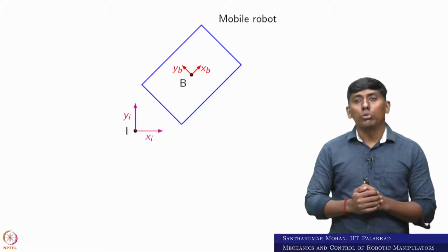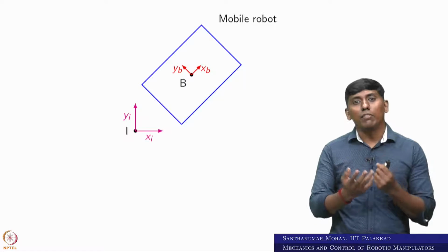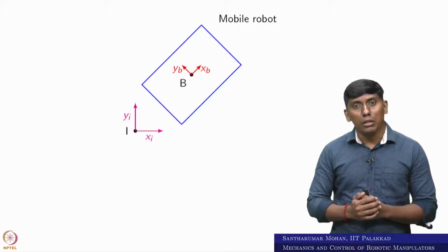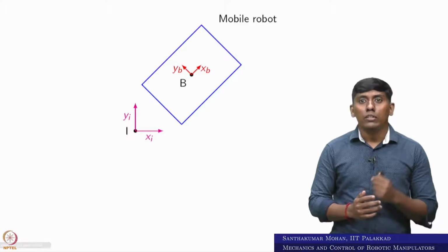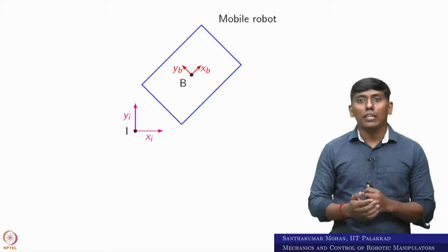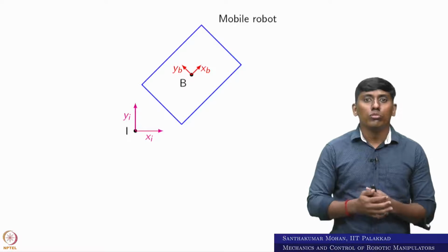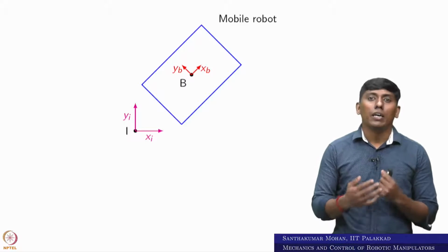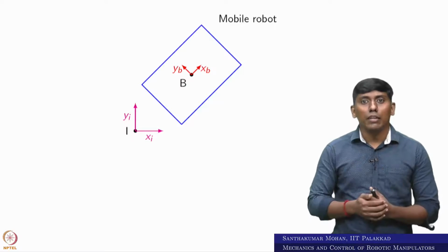But if we talk about Denavit-Hartenberg, there are several constraints. What are the constraints? Denavit-Hartenberg says that every link should be a binary link, in the sense that only two joints are possible for one body, such as ground to 1, then 1 to 2, and it keeps going like that. But here it is not like that; there are three joints. The second consideration is that every joint is supposed to be a 1D joint, but this is a planar joint. So obviously you have to make some modification to the frame arrangement. We cannot take it straightforwardly as RB with respect to I and PB with respect to I, that may not work in the Denavit-Hartenberg approach.